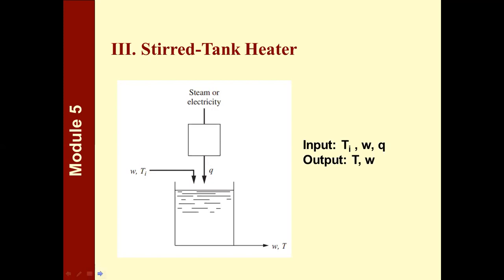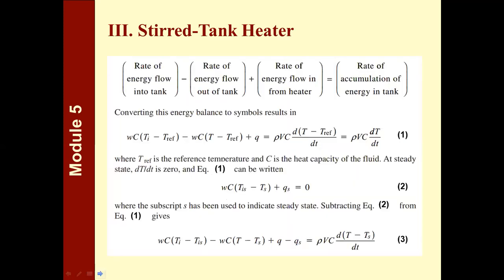Now, if you're going to write the model DE for this stirred tank heater, you will still follow the same formula, but this time it is comparable to the formula that we have in your kinetics. So we have the rate of energy flow into the tank represented by this one, and the rate of energy flow out of the tank represented by this one. So this is for the fluid entering, and this is for the fluid leaving the tank.